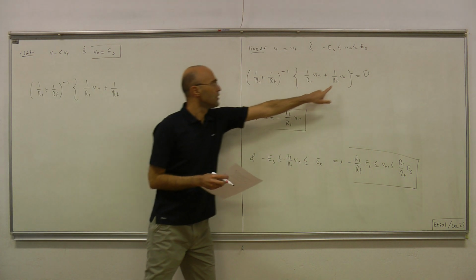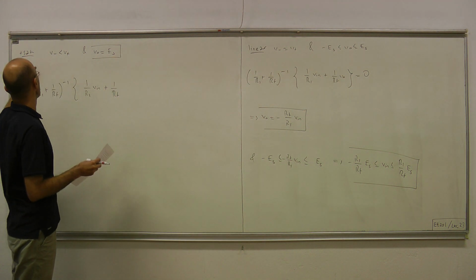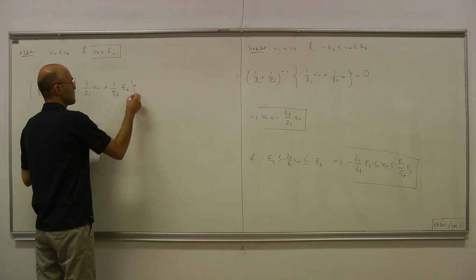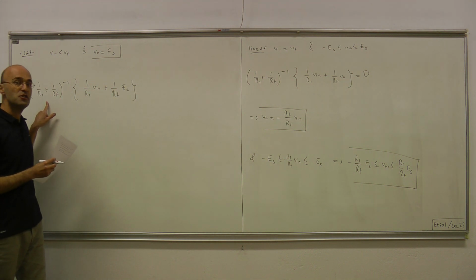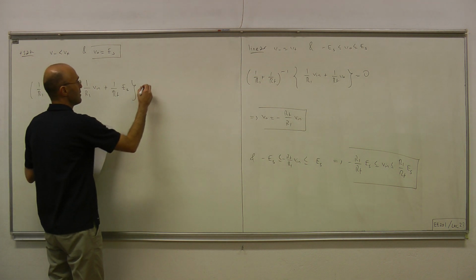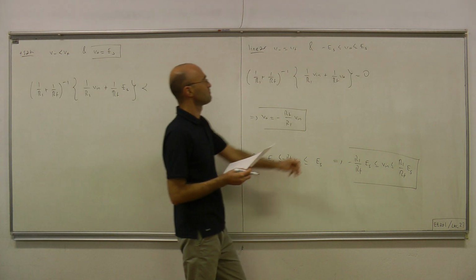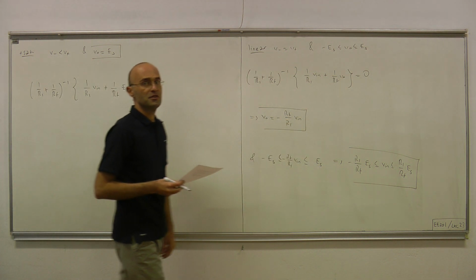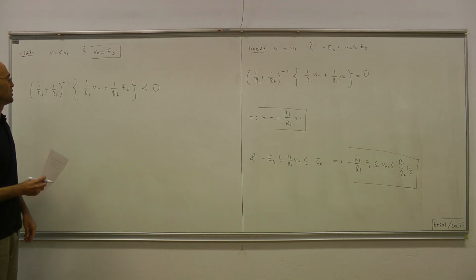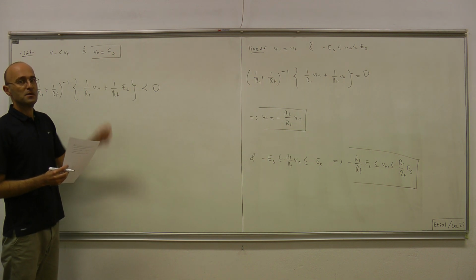Now, instead of writing V out, we directly write ES because we're considering the positive saturation region. So in the positive saturation region, this is what V minus is, and that has to be smaller than V plus, and V plus is 0 at all regions because of the connection. And this is the condition on input voltage for which the op-amp is in the positive saturation region.